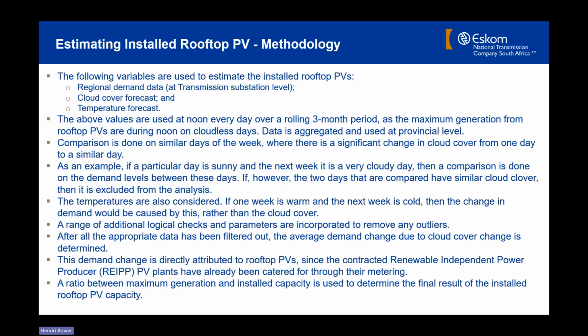Now, also consider temperature. This is a very important variable, and temperature is a very big driver in terms of demand. So one needs to be very careful when doing this analysis that, if 1 week is warm and the next week is quite cold, then that change in demand will be attributed to the temperatures that have changed rather than to the cloud cover. So I'm only using similar days in terms of temperatures, in other words, similar temperature ranges, but then with a significant change in cloud cover.